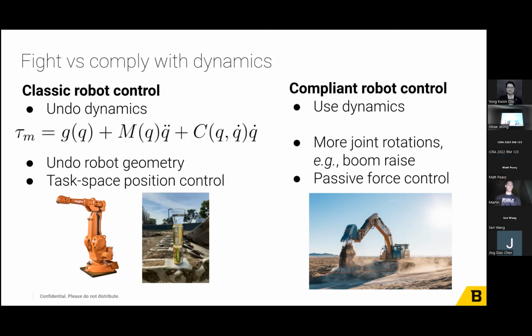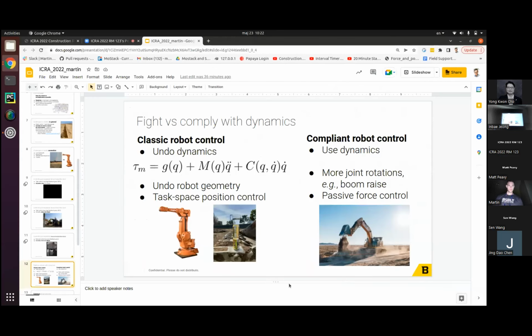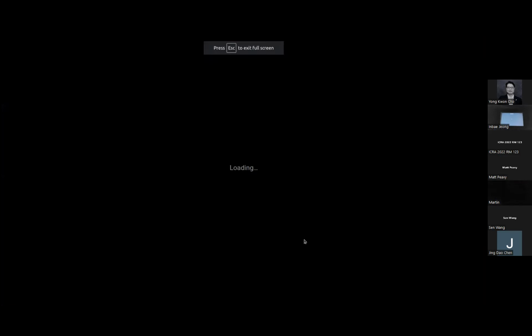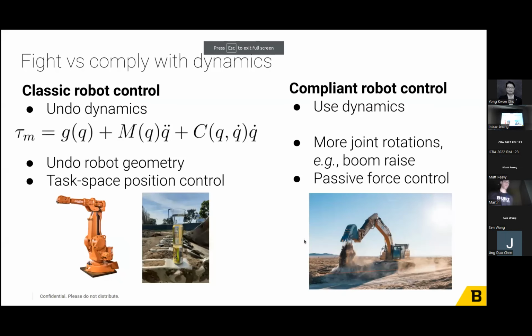So try to invent some joint torque that takes care of things like inertia, gravity, Coriolis and centripetal forces. Once we have done that, then we invent some reference acceleration, for instance, for the tooltip of the robot, and then move it around in a position control style.